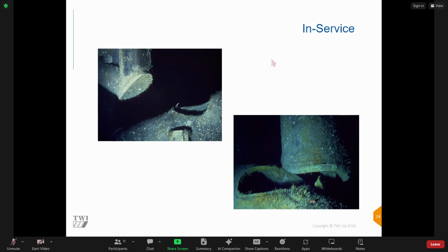Yeah, and then to me, the crack started on this side here. Okay, and then it looks like it's propagated round from that point, to about there, and then you can see that bit there. It's quite a raggy edge, so that's our plastic deformation. Okay, so that's showing ductile failure.